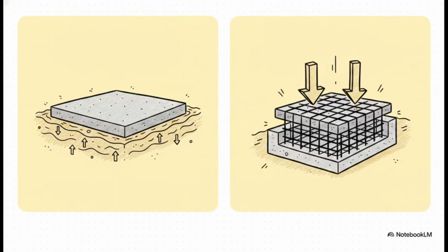Moving on to Section 2, Service versus Factored Loads, the two languages of design. You know, to design a proper footing, you actually have to be fluent in two entirely different engineering languages. Geotechnical engineers speak the language of service loads, or allowable stress design, ASD. We use these raw, unfactored loads to determine exactly how big the footing's footprint has to be so we don't sink or cause soil failure.